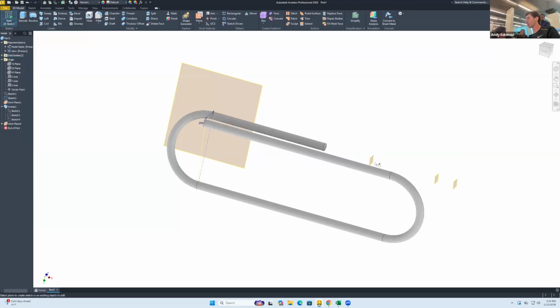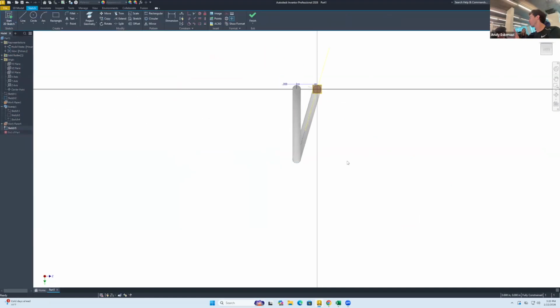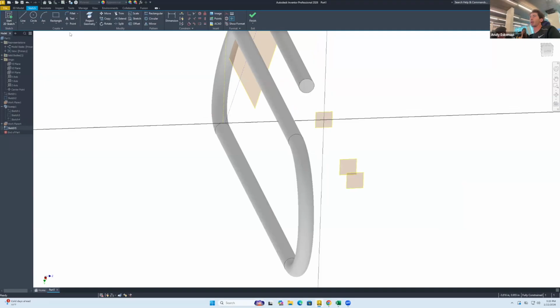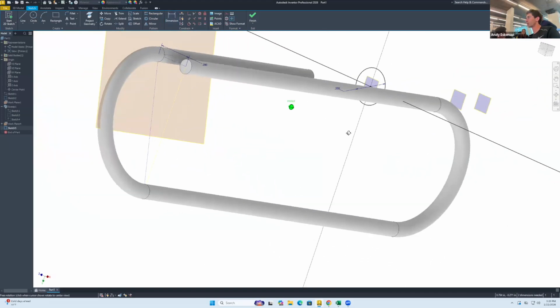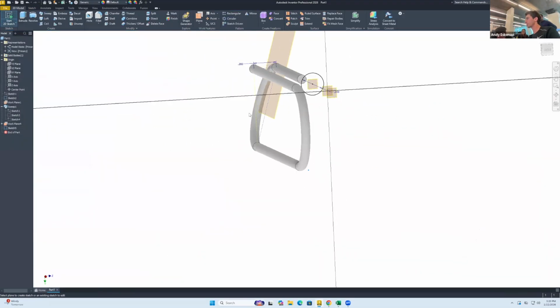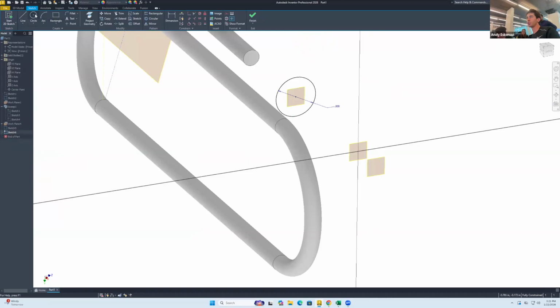But now we do start sketch on this face. By the way, when we do the banana, it's a very similar technique of creating multiple planes and creating the frame. But we know that that's 0.8, which means I'm going to make a circle in here that's going to be, let's start by making this 0.2. And okay, it seems to be fully constrained to that position, so we'll say finish. Now let's do another sketch in here. And let's make this one more. Let's make that 0.5.